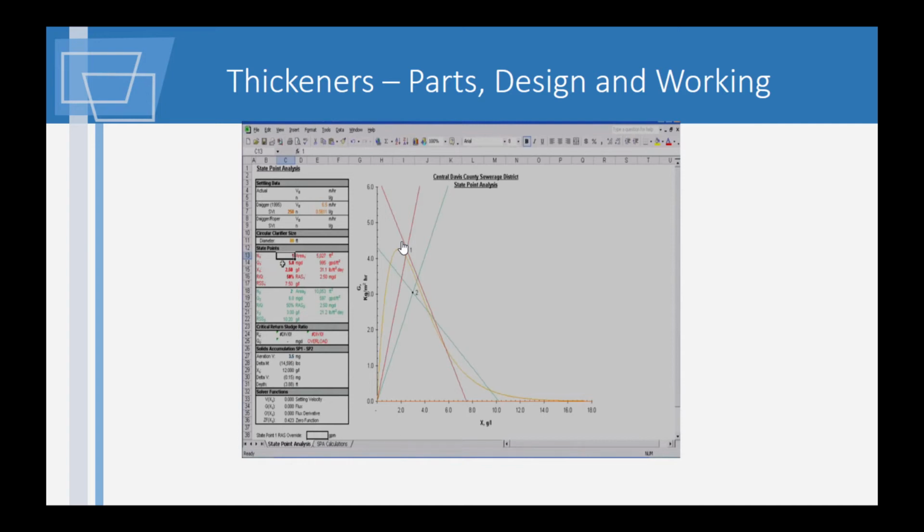For this scenario, let's have everything going smoothly with an influent flow of 3 mgd, a RAS of 50% of the influent flow, and a mixed liquor concentration of 2,500 milligrams per liter or 2.5 grams per liter. Let's clear the second state point values now so we can focus on our single state point. And as you probably noticed, this model adjusts the graph automatically and immediately, allowing us to quickly evaluate how things are going.